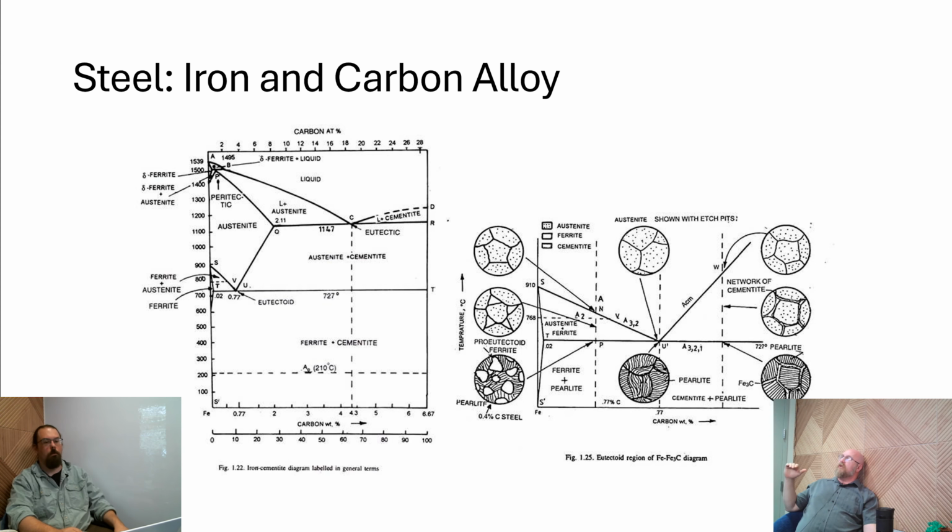So when you're looking at this, keep in mind that these are how the phases organize themselves at different mixtures at different temperatures. What it means in practical terms is if you're elevating the temperature of a solid steel alloy in the presence of any carbon, it will absorb that carbon to lower its melt point. And it's actually violent. All of a sudden it just starts making a puddle, blows a hole in the side of things, sort of like a slagging hole in the side of things.